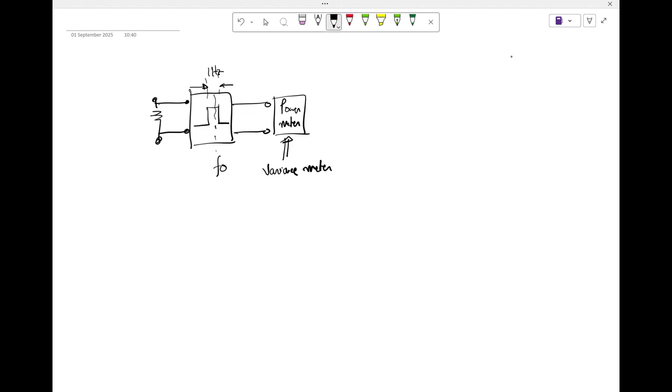Okay. And we observe the output. This output is always 4kTR, right? This power, the variance that you are going to observe, is always 4kTR, regardless of the position of f naught. Which essentially means that if I vary f naught, let's say I check it at 1 megahertz, I get something. I take it at 10 megahertz, I get something, and I do it for all possible frequencies. Whatever we are getting, the variance will always be constant, and it's a flat line.